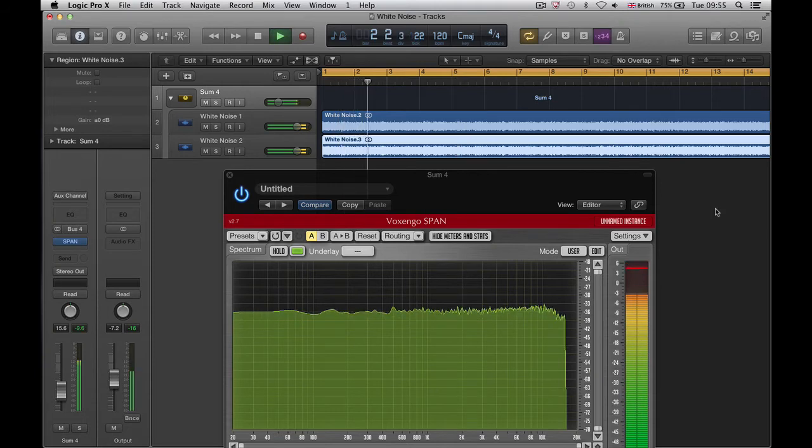There's the equal energy across the spectrum. There's one sample delay, and you can see the top ends come down a bit. 2 sample delay, and there appears a cut at maybe about 12k. Another 2 samples, now on 4 sample delay. That cut's moved down a bit. Now on 6 sample delay, and we're getting 2 cuts.